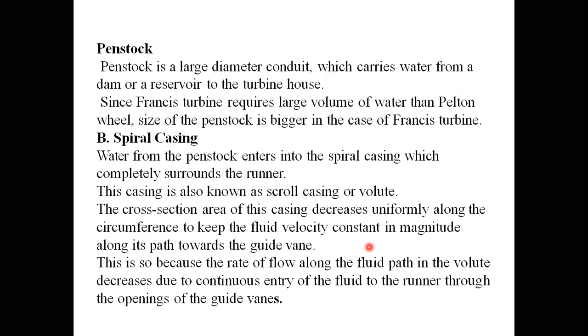See here, penstock is a large diameter conduit which carries water from the dam or reservoir to the turbine house. Since Francis turbine requires a large volume of water, the size of the penstock is bigger in case of Francis turbine. This is the spiral casing.